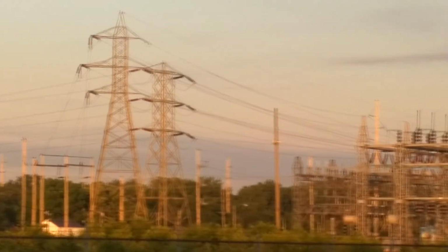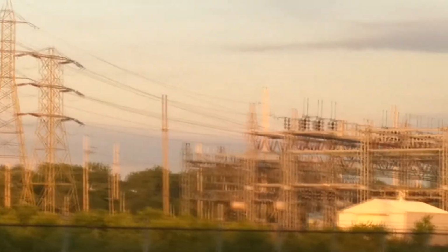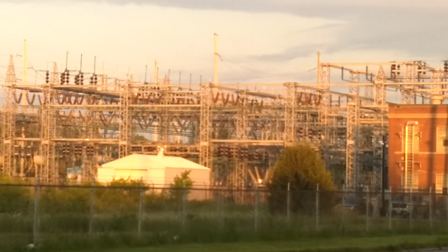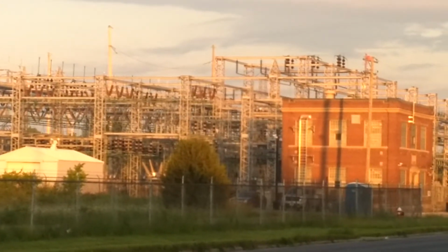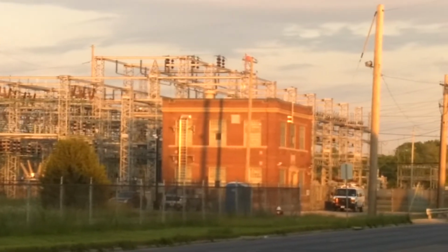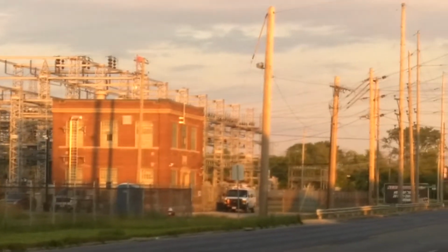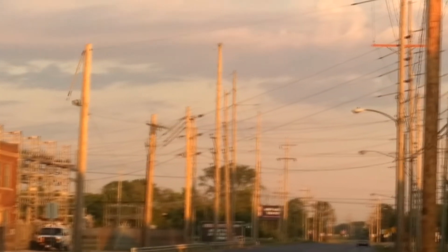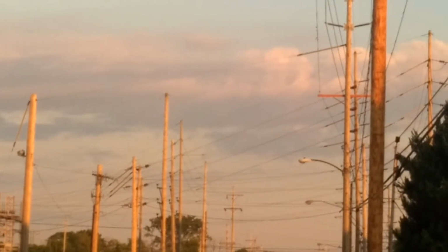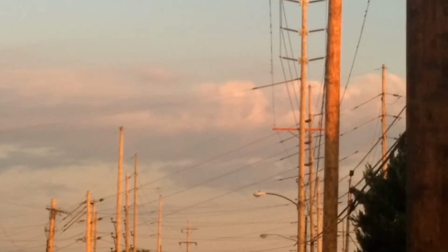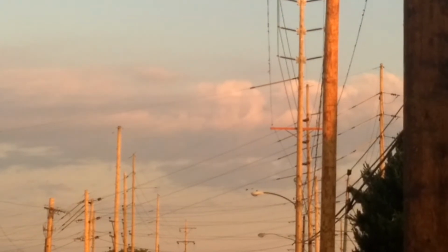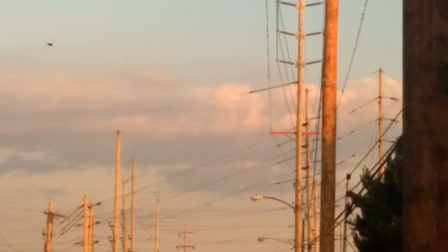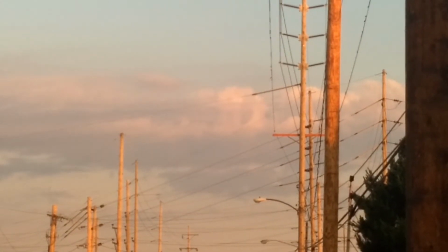Here we see the 345 kV transmission line coming down into a substation on the edge of town. Transformers in the substation reduce the 345 kV down to 13.8 kV for local distribution and to 69 kV for distribution to smaller substations in town. At these smaller substations, the 69 kV is reduced to 13.8 kV for distribution to customers near these substations.